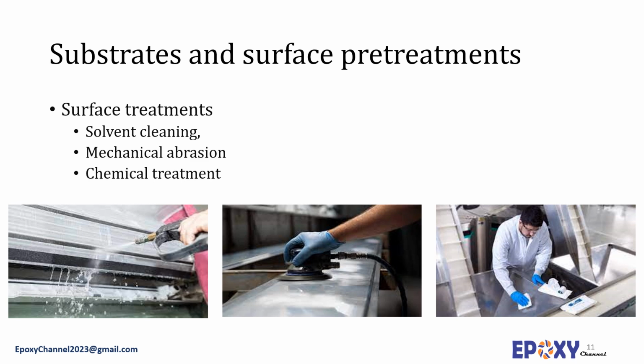As the adhesion occurs within a few molecular layers of the contacting materials, the substrate surface must be treated for efficient intermolecular interactions. The level of the desired strength, the expected longevity, the service environment, and the nature of the substrate determine the severity of the required surface preparation. The main surface treatments employed for adhesion processes are solvent cleaning, mechanical abrasion, and chemical treatment. The ultimate aim of all these methods is to increase the surface free energy of the substrate and promote adhesion wetting.